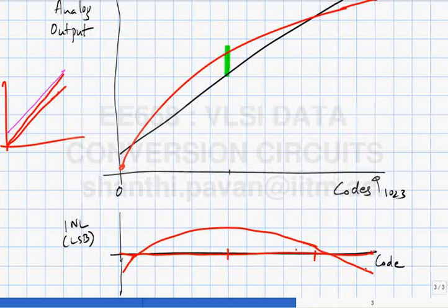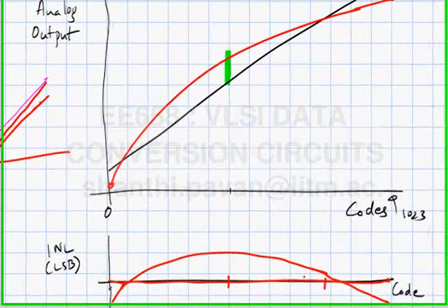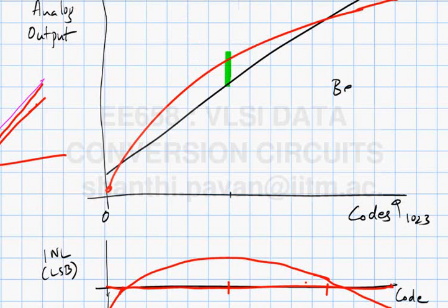So if you see an INL which is always positive, what can you conclude? That basically means that offset and gain errors have been corrected for, alright. So there is always a possibility of improving the, it's the same converter, okay, so it's just a matter of specmanship. So you can always do better by removing gain and offset errors. So this is what is called the best fit DNL and INL.